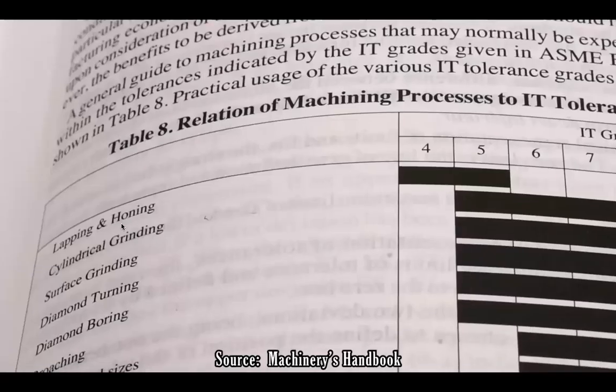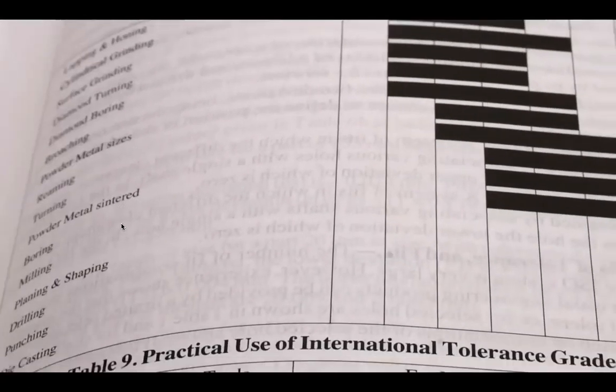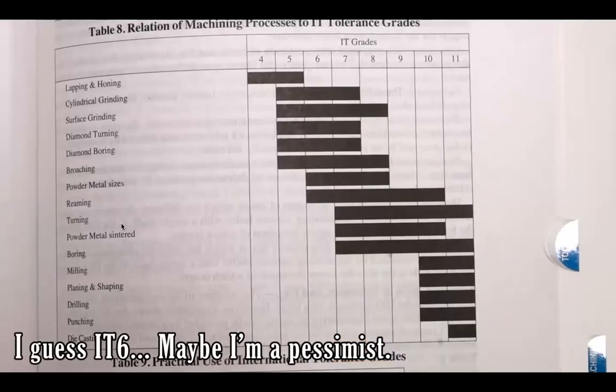Every manufacturing process can be statistically analyzed and an IT number can be determined. This means that if I'm reaming a hole, I can look up the reaming process and see that at best I can achieve about an IT7. So I can't specify an H5 or a G5 hole if it's going to be reamed.